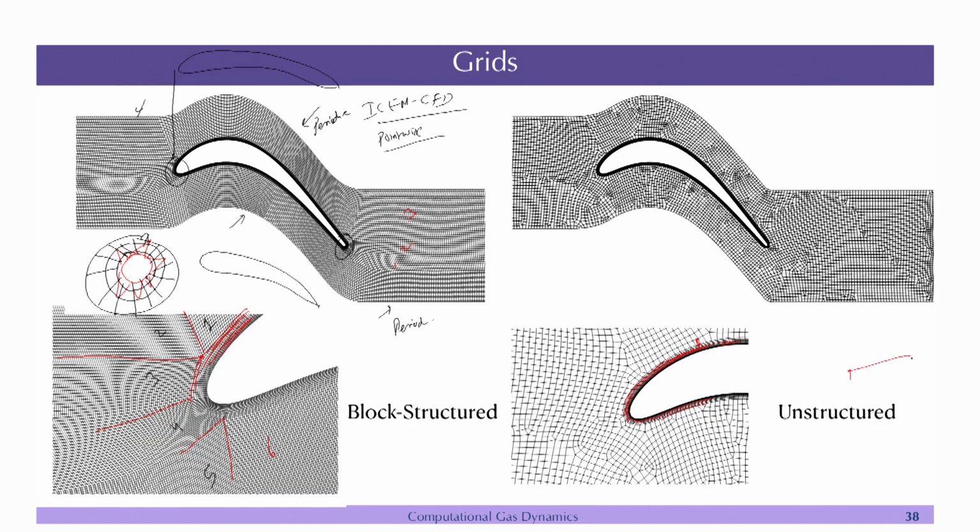If the transition is very high, then again there will be loss of accuracy, and sometimes the code may blow up also. The skewness should not be very high, because elements that are very thin and going like this should be avoided. So, there are some guidelines in creating meshes.